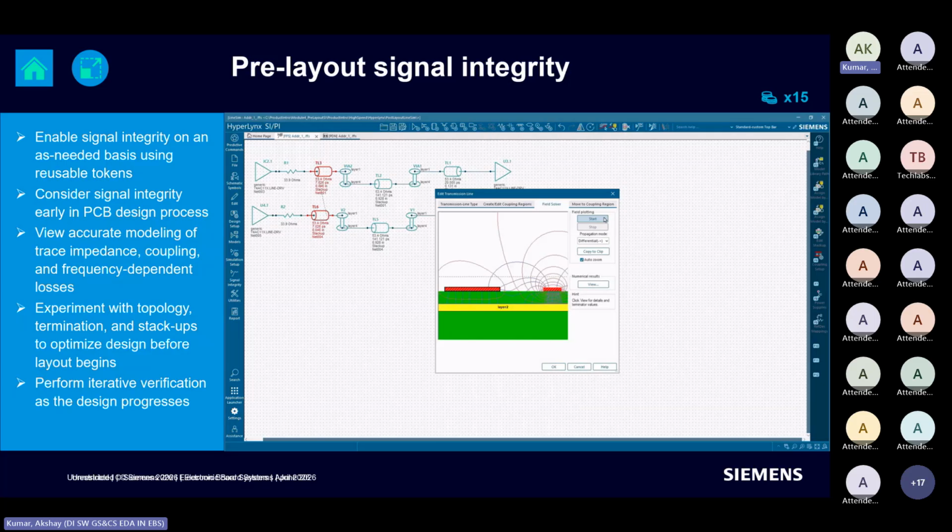So with that, you will be able to perform signal integrity at your schematic level. This is a very basic feature set, which will include stack up editing, the termination wizard, transmission line support, and also the sweep manager. All these things are included as part of pre-layout integrity.